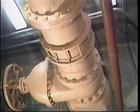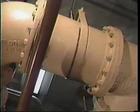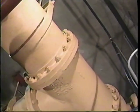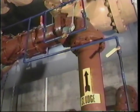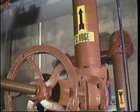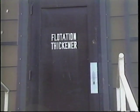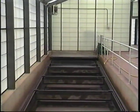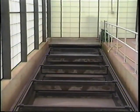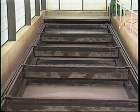A portion of these solids may be wasted into a biosolids handling facility for the purpose of digestion. Primary sludges and trickling filter sludges will usually be placed into a biosolids handling unit, which will facilitate digestion. Before being placed into a digester, the solids may pass through some type of thickener, such as a dissolved air flotation thickener or a gravity thickener, in order to remove as much water as possible.